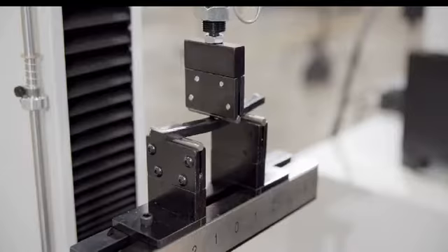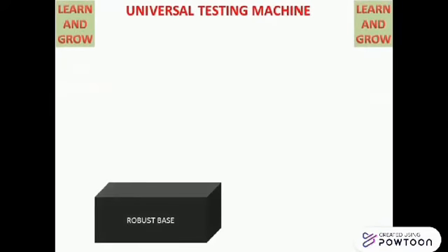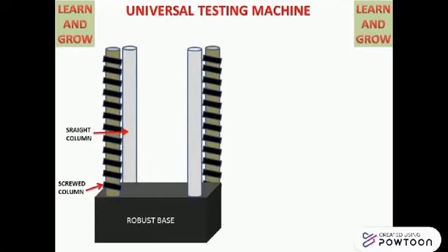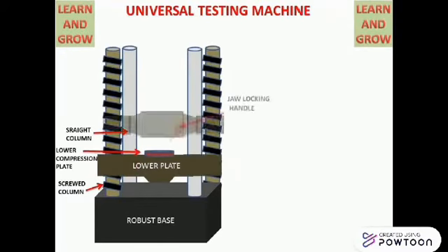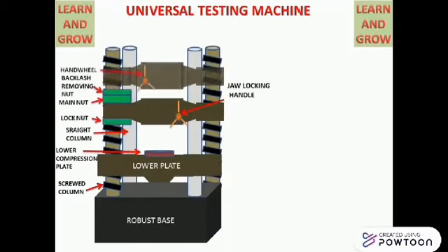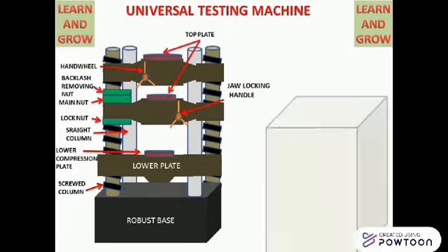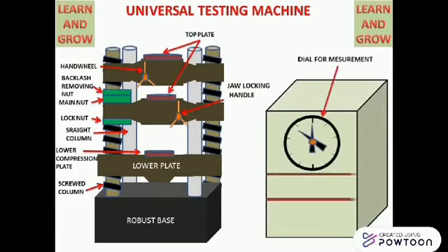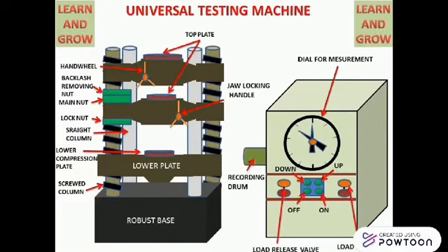These are the minor parts of the host machine. 1. The cylinder was fixed on bottom support with bolts. 2. The piston was fixed on work table while work table supports column. 3. The screw crossed over work table down end was fixed on bottom and the up end was connected with up crosshead. 4. There is a remote box button at the lower crosshead so it is easy to adjust the original test space and can clamp the upper and lower clamp automatically and column lift upper crosshead to achieve tensile, compression, and bending tests. And 5. The machine controller is one that processes the data of materials being tested, stores, and displays the test data.